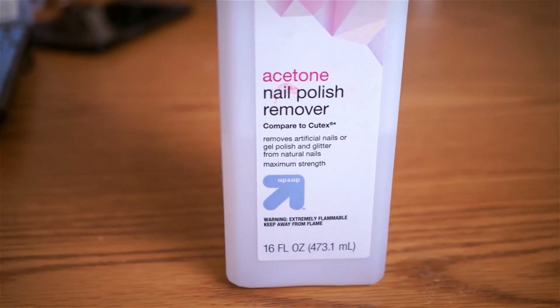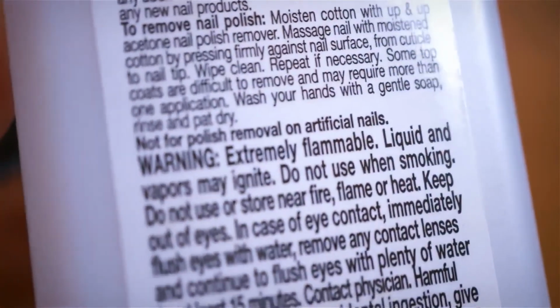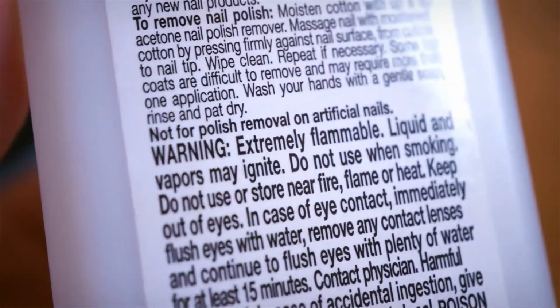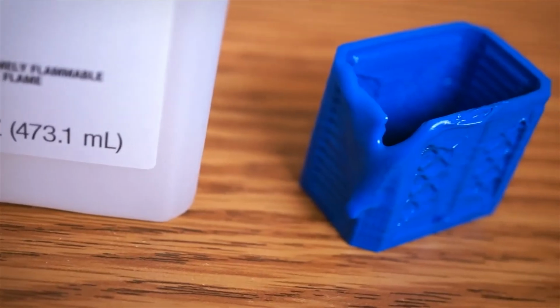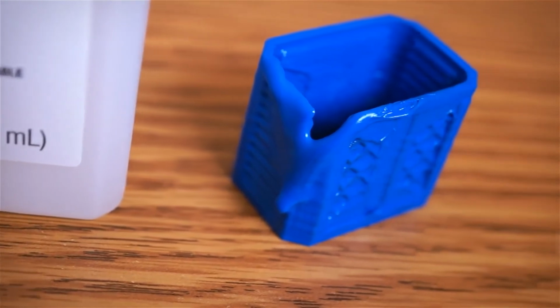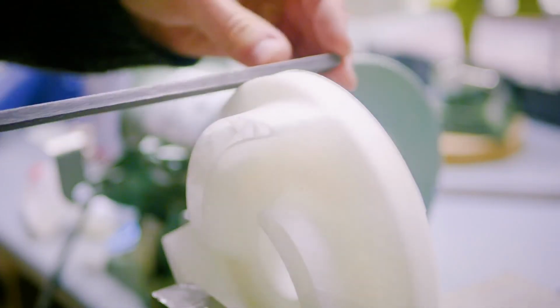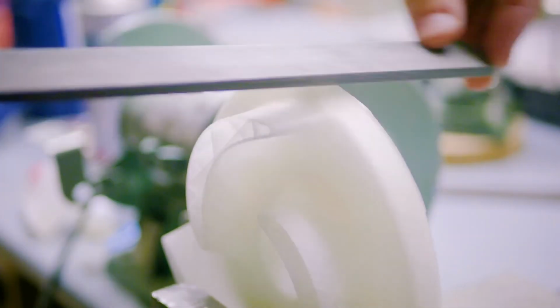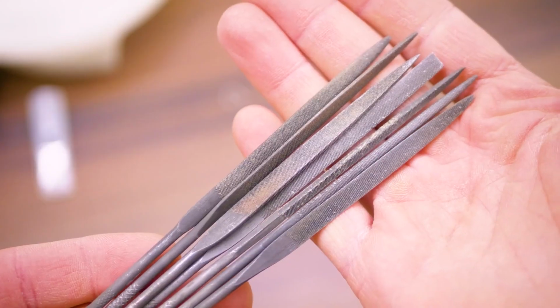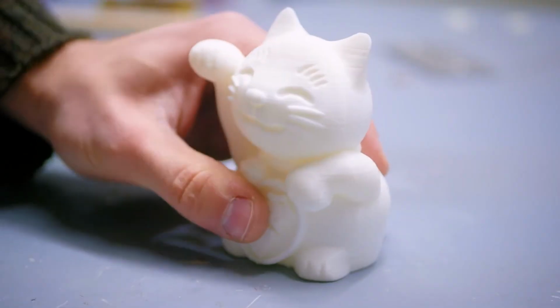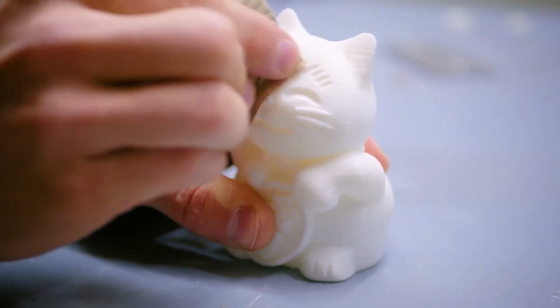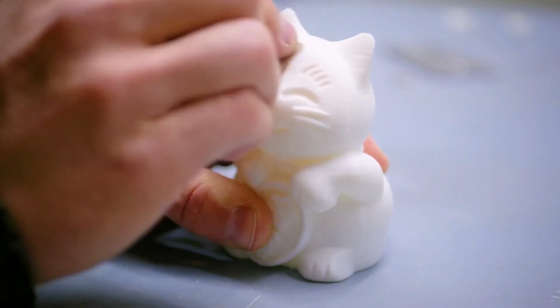A lot of people online will use acetone, but I want to make particularly clear that this is a last resort and I don't really recommend it. It can actually melt your parts as well as being very, very toxic. I like to recommend some good old-fashioned filing to take down some of those sharp edges, especially if you can get your hands on some of these little files. Even a nail file will get most of that off for you. On larger areas, you can use some wet to dry sandpaper as well, and that'll come up pretty smooth.